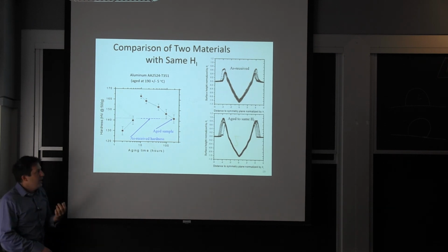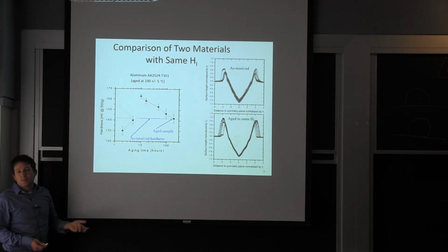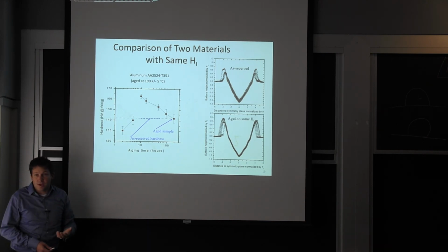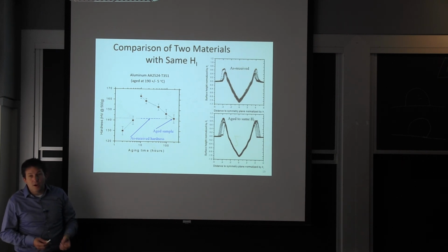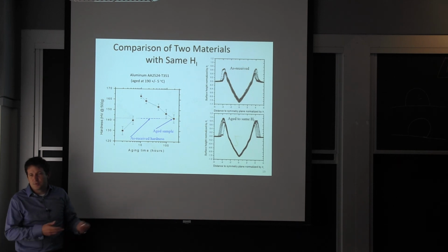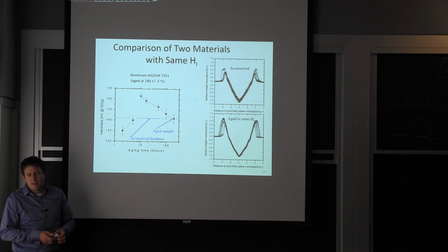So it's a way to show you how important strain hardening can be in terms of wear resistance, for example. If you really want something that's wear resistant, you're looking at bearings. We use a lot of precipitation hardening stainless steel for bearings. And without going through all the details, it's the same thing. You start forming very, very little particles in the matrix of stainless steel, the same way that we discussed today for the aluminum.